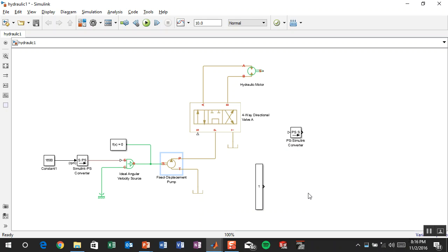I think I told you guys one time, a lot of my work is with tree shakers, so it's like 20 G's at 35 hertz. Maybe 30,000 pounds of force out the trunk, and I can't get an electric motor to live. But maybe they're there, maybe they're coming. What's that? Thorium? Can't hear you. A thorium reactor? I don't know what that is. Are we talking about science fiction now?